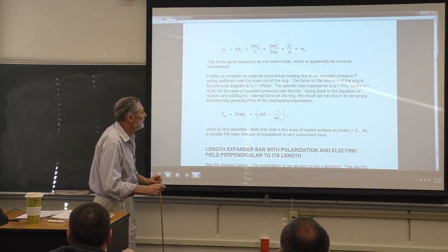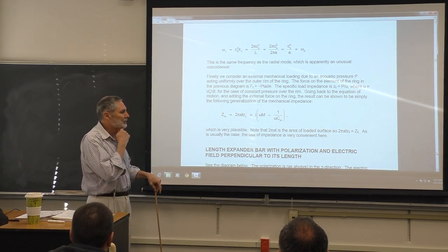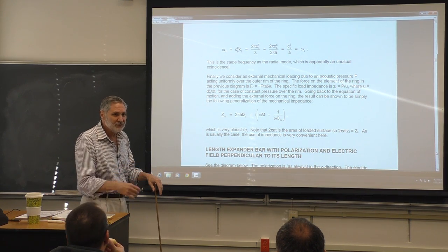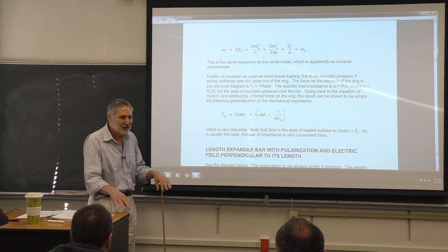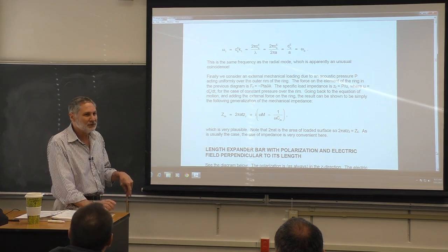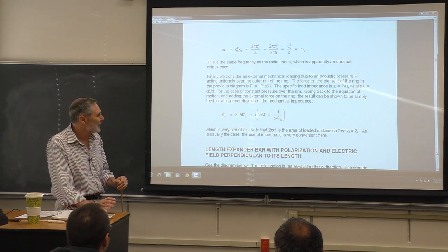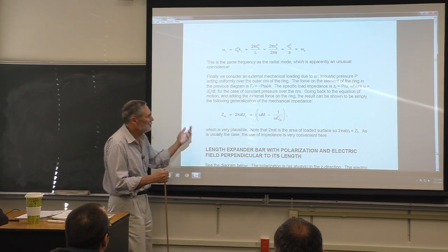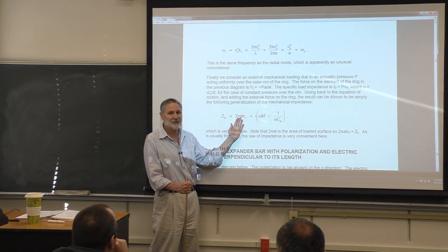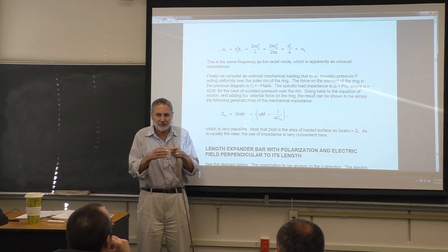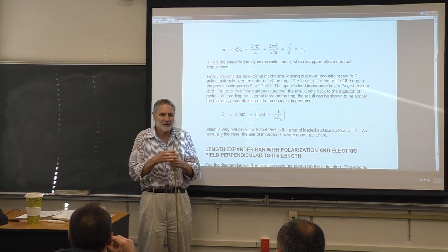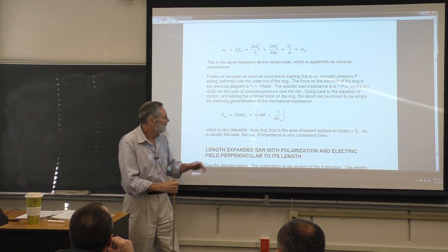Now, if you go back to our equation of motion, you can add this in, in Newton's second law. But at this point in this sequence, you should have a strong suspicion of what's going to happen here. You can show that it appears in the mechanical impedance as a resistance. Because this is a resistance, right? You're radiating sound. It's energy that's going away. It's not coming back. So this is a purely resistive load.